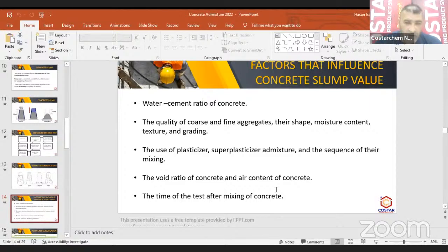Okay, what else will air do for me? Freeze-thaw cycles. It will enhance them dramatically, which again falls into the durability factor of your concrete. Also contraction and expansion of your concrete element, and definitely air entraining will help a lot with it.